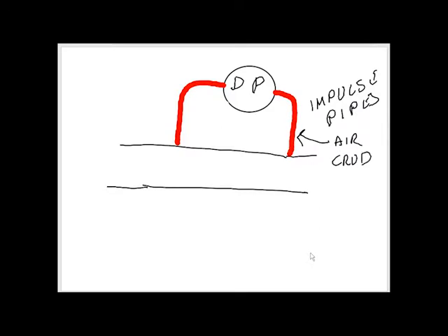And our main call out is we go in and we bleed the air out of them, or we blow high pressure air or high pressure water through them to clean the crud out. That's a problem we get with this type of system. That's something to bear in mind if you've got them.